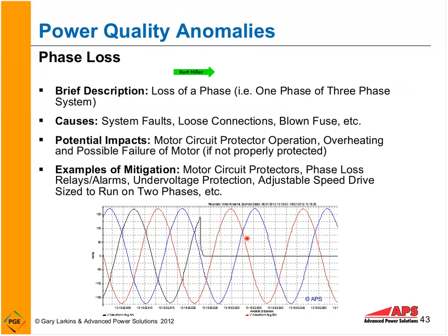Three-phase motors might continue to run if the motor circuit protectors, the proper protective relaying, have not been put in place. So in this case, the motor may start to overheat. In many cases it will, in some cases it will burn up the motor. So all systems should have some type of motor circuit protector, overload protection, or there should be phase loss relays in there.